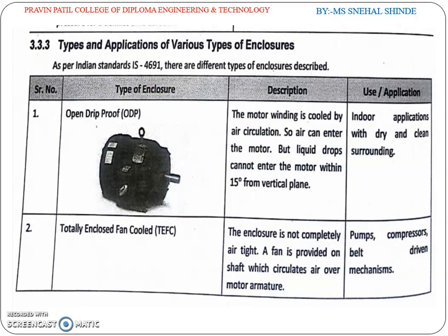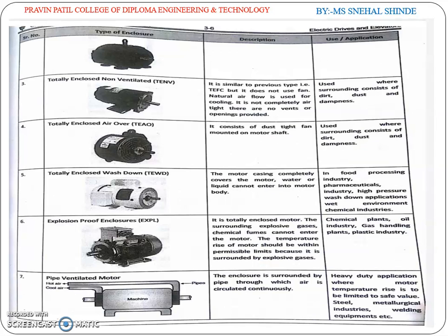Second is the totally enclosed fan cooled, TEFC. The enclosure is not completely airtight. A fan is provided on the shaft which circulates air over the motor armature. Applications are pumps, compressors, belt driven mechanisms.